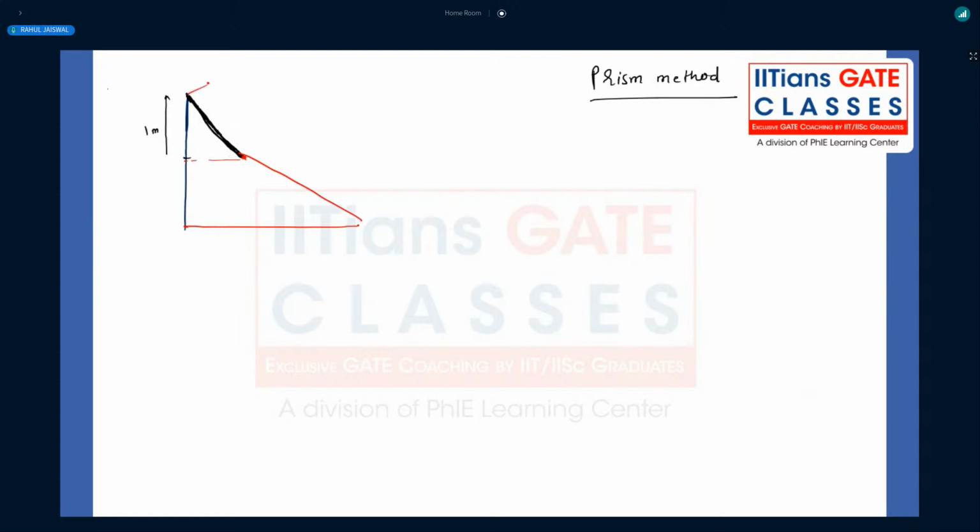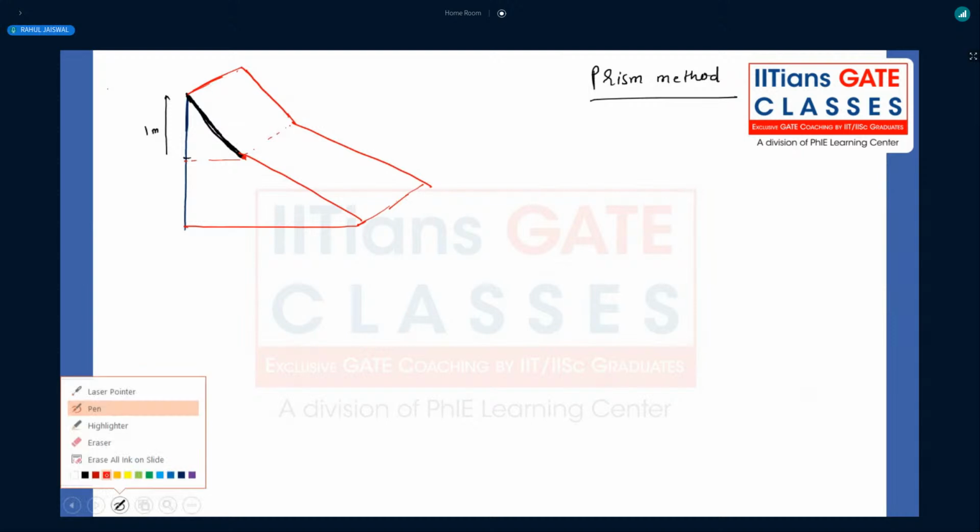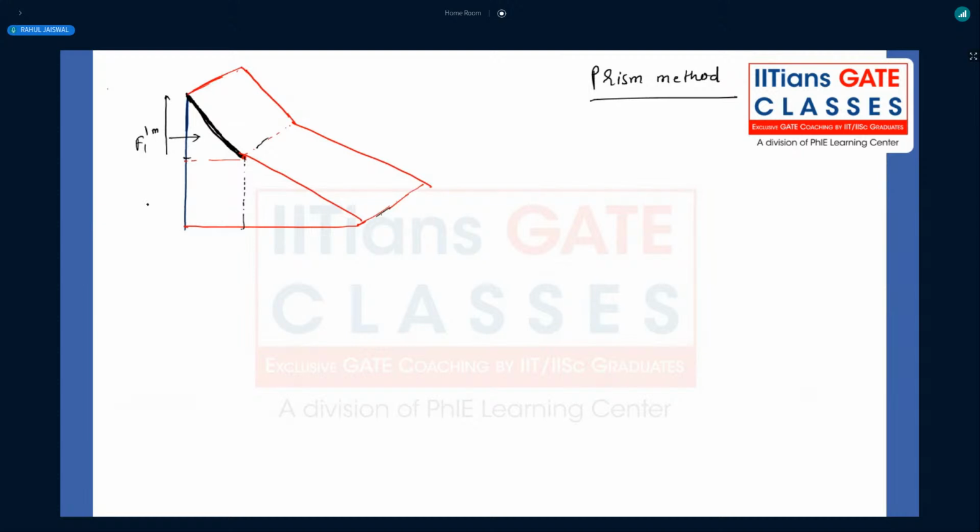So if you just construct the volume of the prism, it will be something like this, right? And now if you just think of the calculations, now it is very easy. Whatever the volume of the prism is there, first of all, you calculate what is the force which is acting here. Then you calculate this particular force. Then you calculate this particular force. And we need to take the moment about this hinge point O, right?